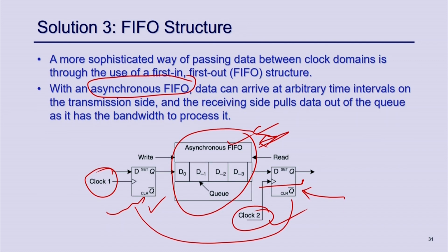And the third technique, the more generic and robust way, is the FIFO. You use a FIFO between 2 different clock domains, and the writing and reading are completely independent of each other, right. So, these are the 3 techniques for the issues that will be faced with multiple clock domains. Okay.